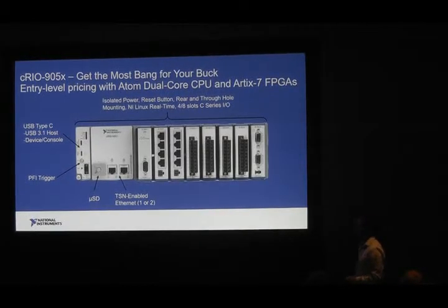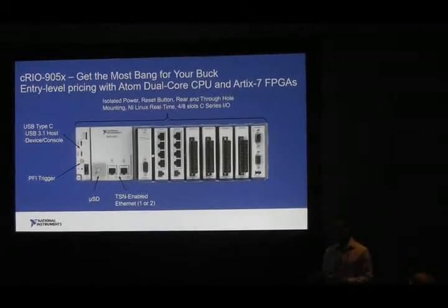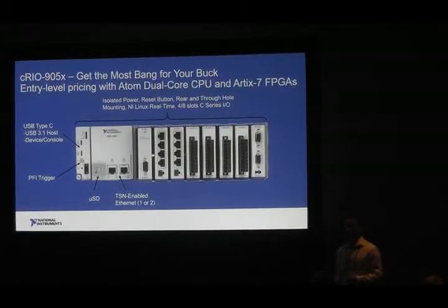And then in a similar vein on the data logging side, we did integrate microSD into this new product as well. The reason being, as we integrate DAQmx, you can expect a lot more measurement applications within the product. And as you have measurement applications, you also need to be able to store a lot of data alongside that. A lot of people like the SD within the existing CompactRIO controllers, and so we've now added a microSD version of that onto our new CompactRIO controllers for the 905X.